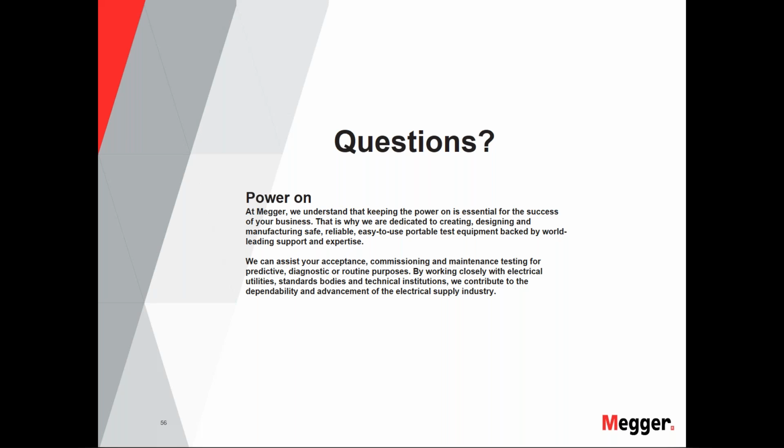However, to answer the question: is it okay to have them coming out of the generator? I would say it's not a matter of okay or not. It's a consequence of physics. Now, the generator step-up transformer, being a delta-star connected transformer, takes care of those third harmonics and insulates the generator from the influence of third harmonics coming from the system, and insulates the system from the influence of third harmonics going out from the generator.